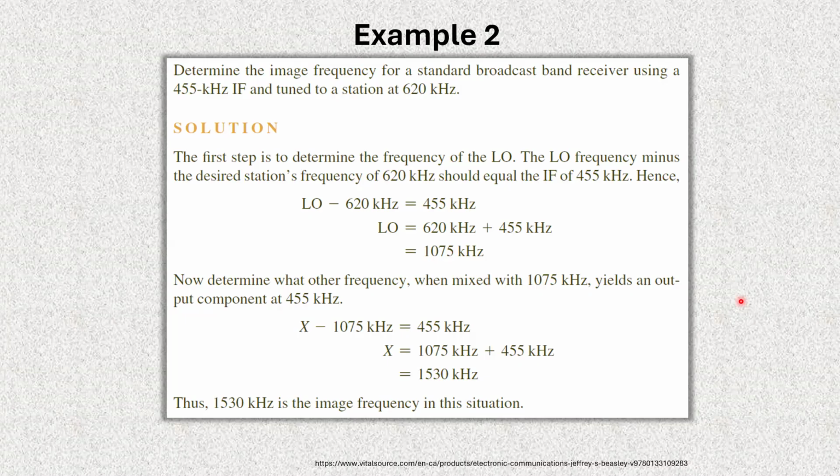So those frequencies of the carriers that belong to each individual wireless microphone being used on the same stage, in the same physical proximity, have to be brought together or used in the same system in a way that they don't hit the image frequencies that could make one wireless microphone interfere with the other.